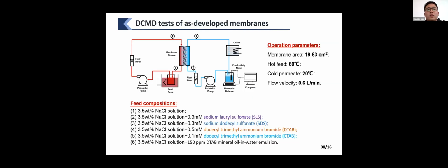The membrane test used the DCMD configuration. The relevant parameters are listed here. The feeds were prepared by adding different surfactants to sodium chloride solution with a mass ratio of 3.5%.